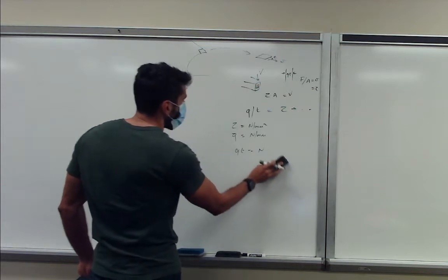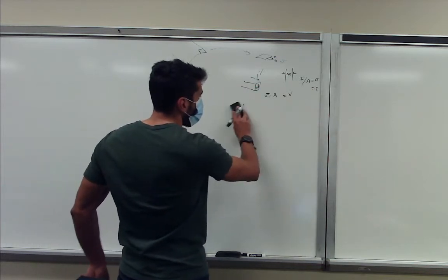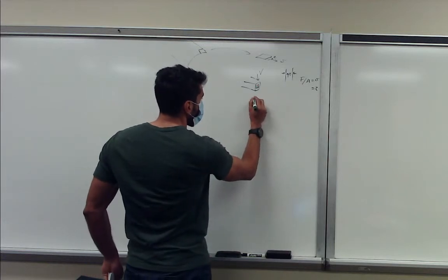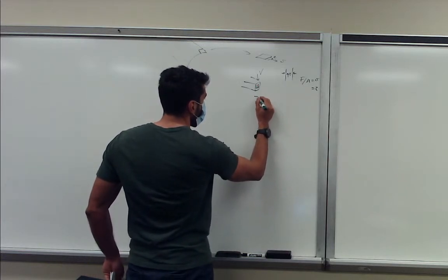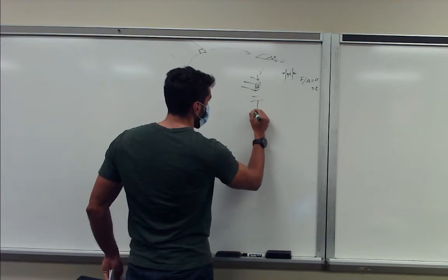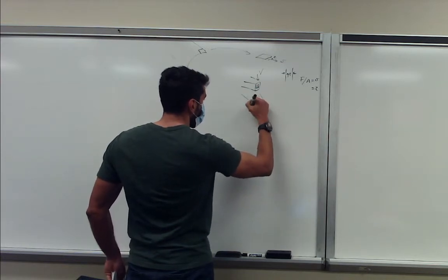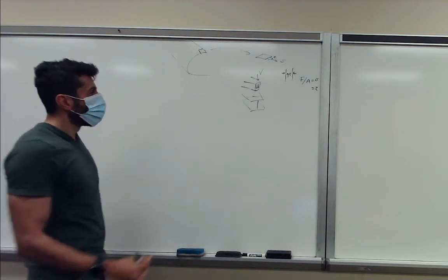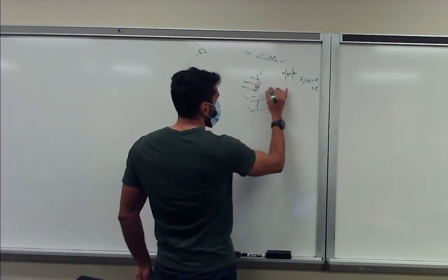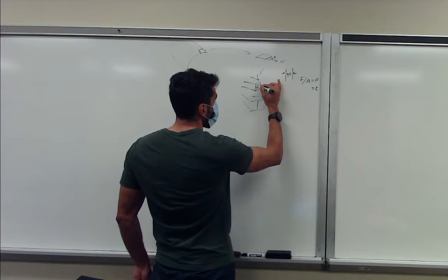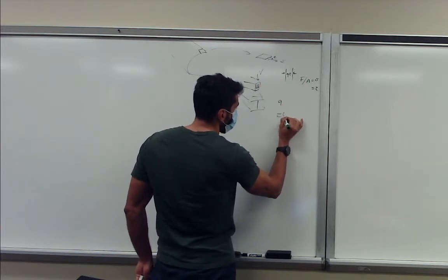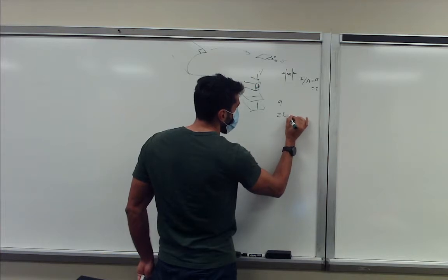So this is how we start, and then we said, okay, well, especially with thin wall structures, say we have an I-beam where the flange thickness is significantly smaller. Then instead of working with the shear stress going through the thickness, we're going to work with the concept of shear flow, which we defined as shear stress multiplied by thickness.